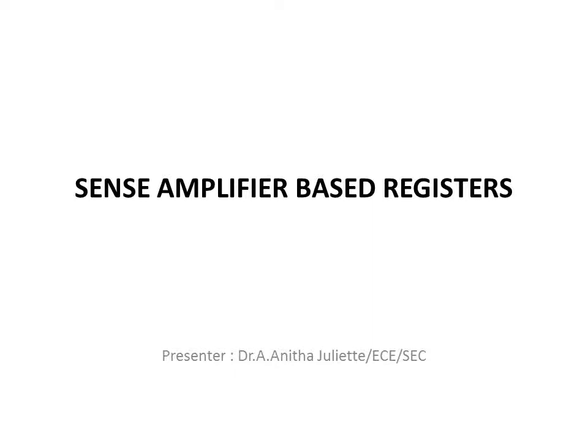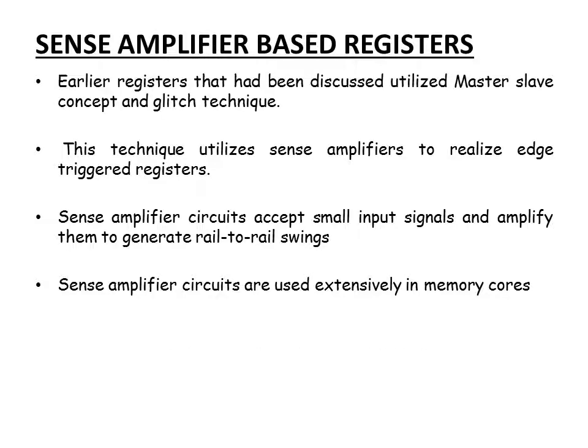Hello students, so today we'll discuss sense amplifier based registers. In earlier videos we have seen registers that were realized using the master slave concept and also pulse registers that used the glitch technique. In this sense amplifier based register, the technique utilized is the use of sense amplifiers to realize the same edge triggered registers.